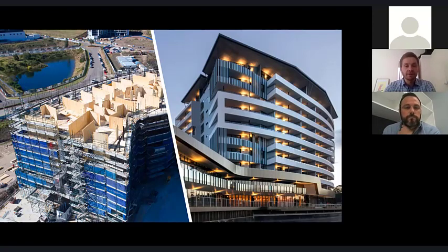Yeah, I think I'll just add, from a design perspective with your facade, it's really important to understand the design criteria. Generally, you're going to have much more restrictive design criteria for deflections and things like that to limit deformation of brittle materials. But it's also worth noting with things like the brick snap system, a prefabricated panel like that is much heavier.